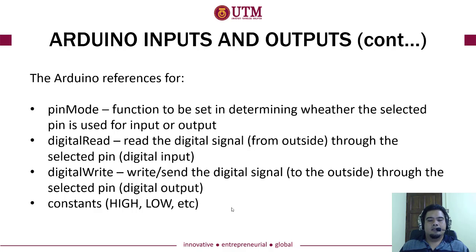If you put HIGH, that represents 1 in binary, or 5 volt if you talk about the real digital signals themselves. Just make sure that you are familiar with these functions, because these are the functions that you need to use in order to design, set, or operate your input and output ports in Arduino.